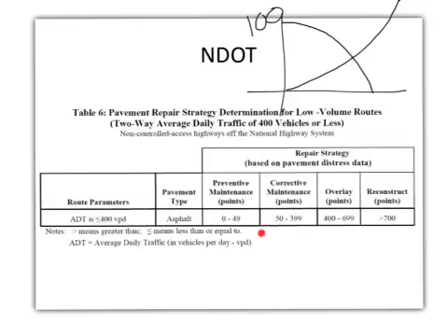As you can see now, the numbers are only from 0 to 49. Once I start to see the pavement is failing, that means the numbers are going to keep accumulating until I reach all the way up here, where this is really connected to the reconstruction, where I have more than 700 points. The maximum that I have seen before was about 1700 as the maximum number of that rating system.